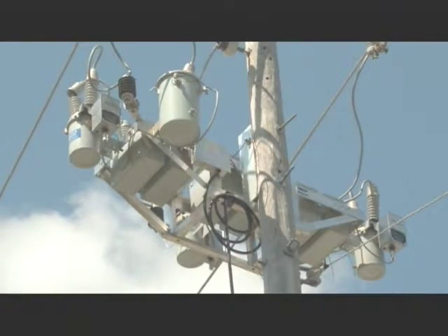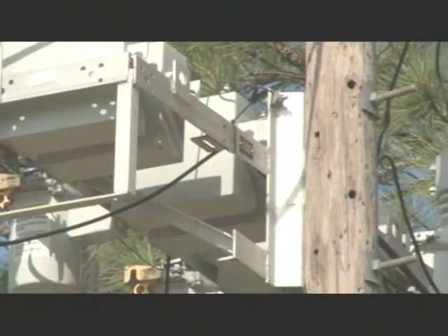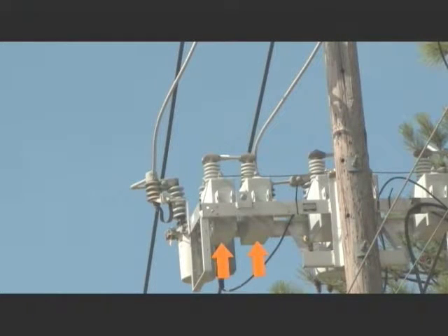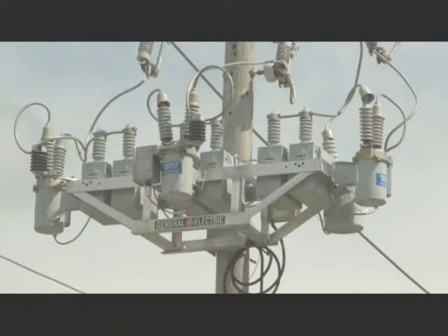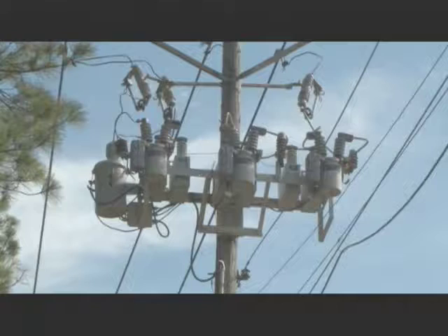The frame of each capacitor bank is made up of metal structural members and is mounted directly onto the utility pole. The frame allows individual capacitor units to be mounted to form the capacitor bank. It is also used to mount other equipment, such as switches, to the capacitor bank. The ground sides of the capacitor units are connected to the frame, which in turn is connected to the pole ground. For safety, the ground should always be connected before the capacitor bank is energized.